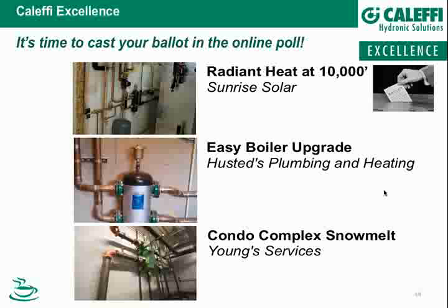My own thought is, as we go into the future, I think you're going to see circulator manufacturers eventually offer both operating modes, both temperature-based algorithms as well as differential pressure-based algorithms, and maybe even special algorithms like drain-back solar applications or other types of specialized.